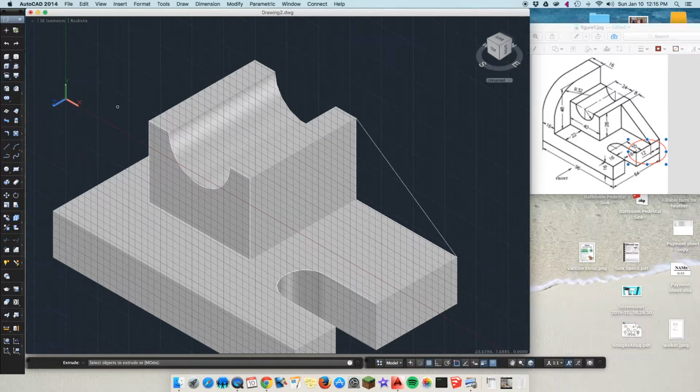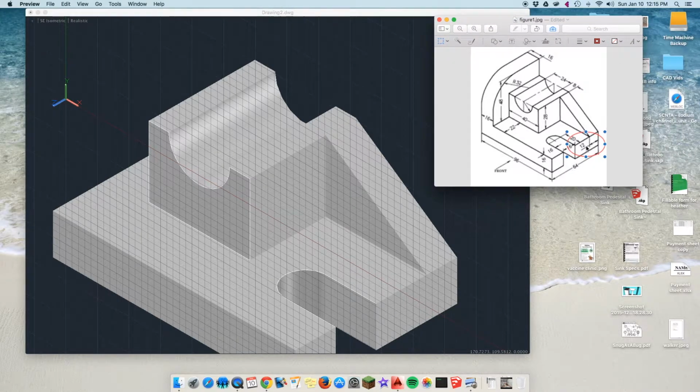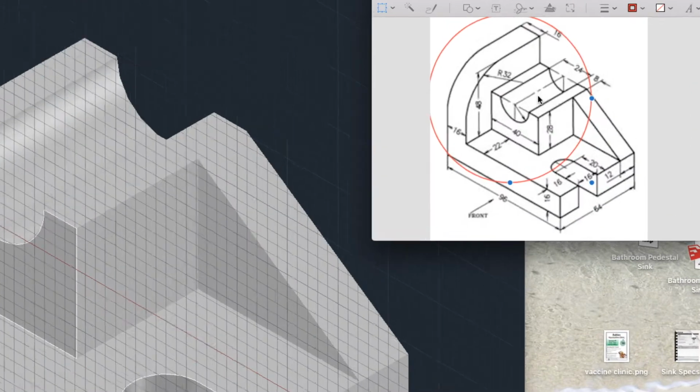So if I click extrude and I click the triangle and then I hit enter, there we go. That's the difference, I think. 12, enter. There we go. Now it's a solid object. Okay. Good to know. Press pull and extrude. All right. So now the last thing we have to do is this whole back section back here, which is like a curved wall, I'll call it. Okay. Zoom in a little bit so you can see it.